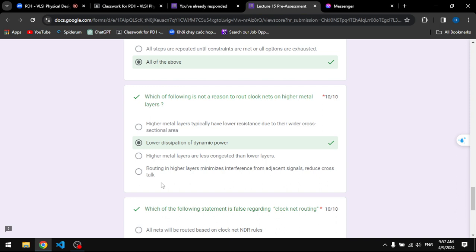Any of these techniques the tools use, you can use manually. Understanding the impact and how to use them, you can go and fix timing or fix DRV by doing this, if the tool can't do it. The reason you come in and touch it is if the tool can't do it, or at the very end of your design you don't want the tool to touch it or mess things up.